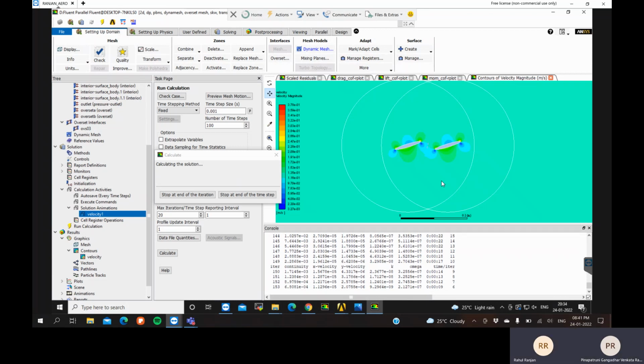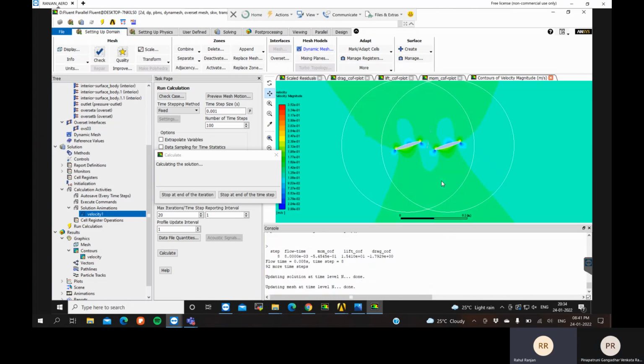I should change it to elliptical or something. Or I should make a single line partition and divide those segments into a particular number of divisions. Then we can get regular size meshes.